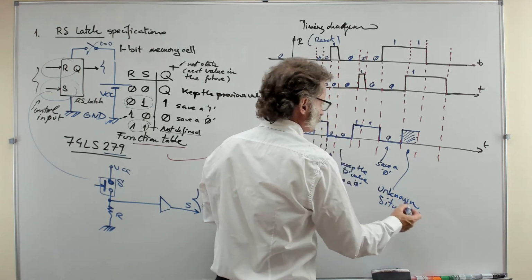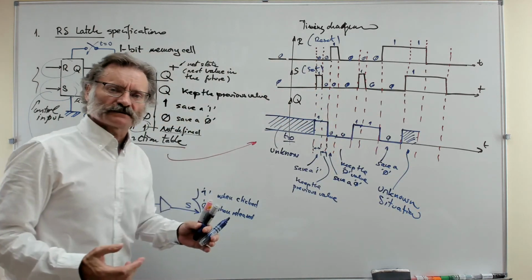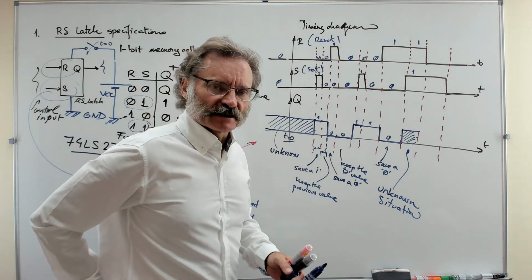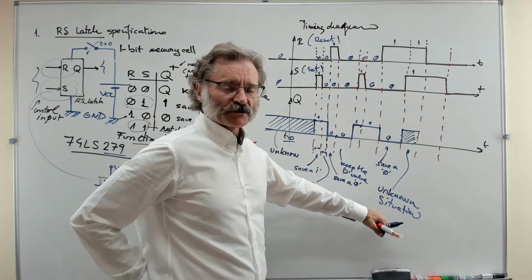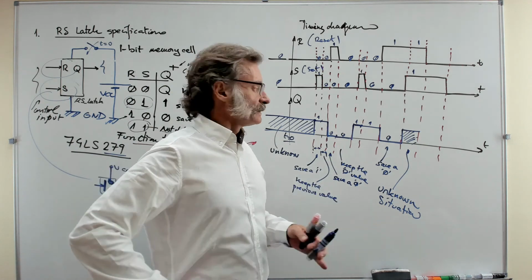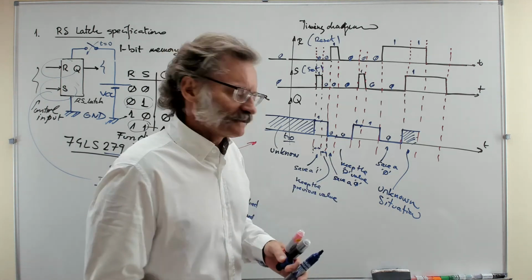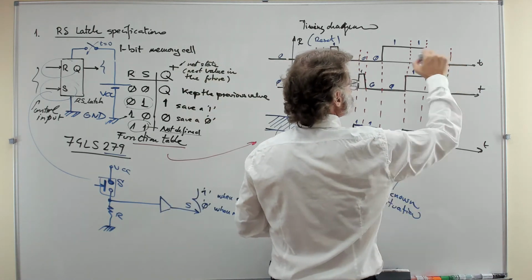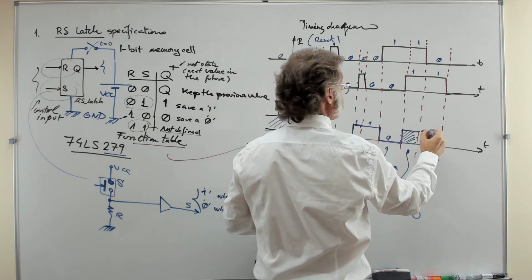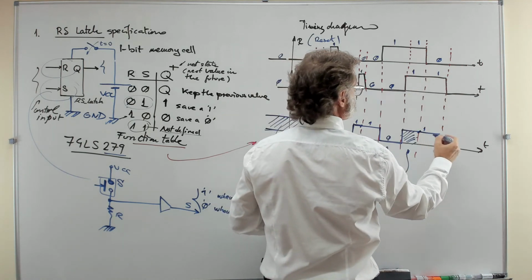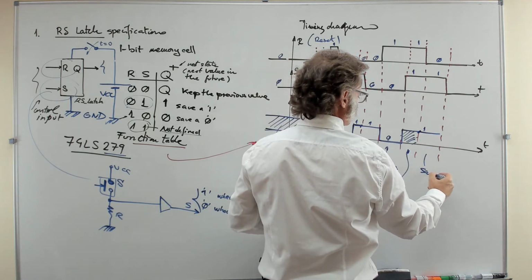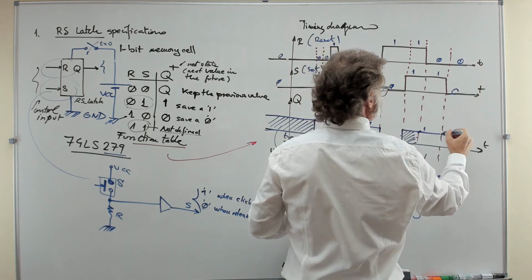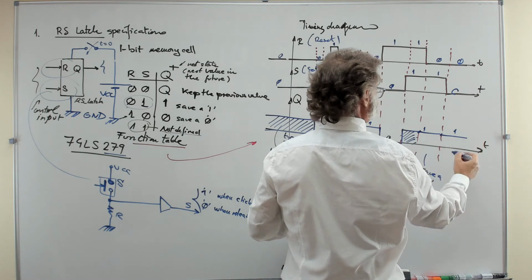So if this circuit becomes part, as a component, of a larger circuit, that is indeed a great complication, because you know nothing about the value of the Q. So you must prevent that situation. So then you do something like this. You see, this is what you try here. 0, 1, so now you kept a 1 like this. So this is safe, a 1, no problem. And then 0, 0, you keep this 1 like that. You see?